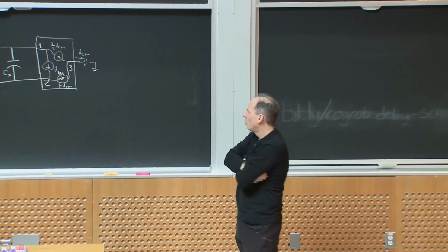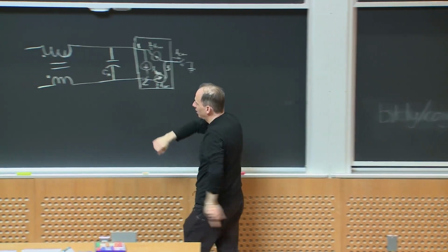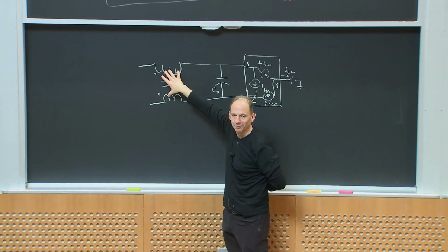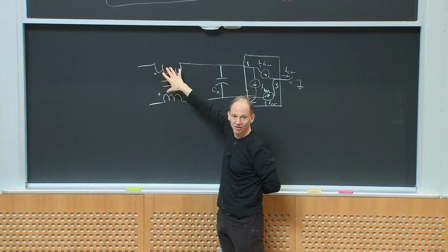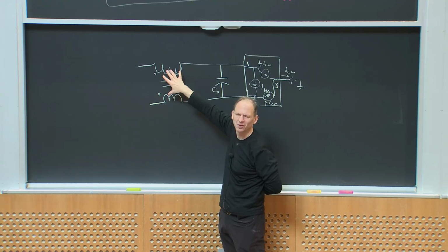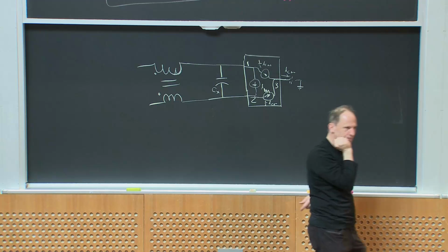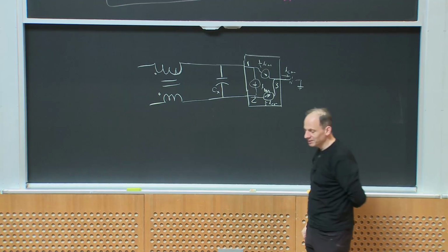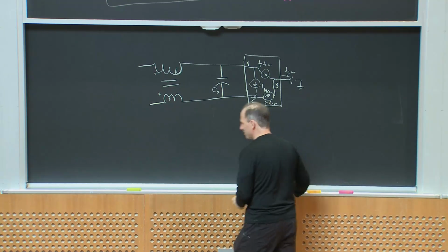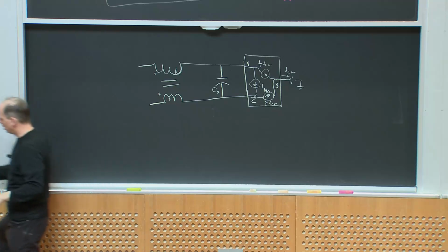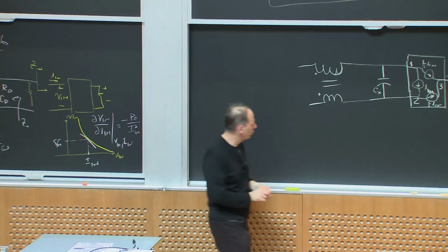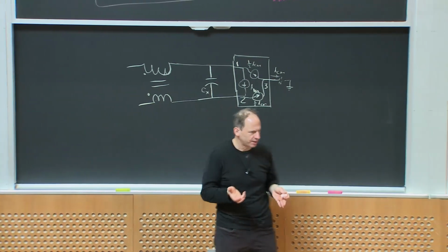Okay? Well, what would I do in my filter design? This thing makes like a perfect inductor against common mode currents, in some sense, if I could go out and buy myself an ideal transformer. Now, I can't go buy myself an ideal transformer. Why? Because they don't sell them at DigiKey. What do I have to think of in terms of parasitics in my transformer?